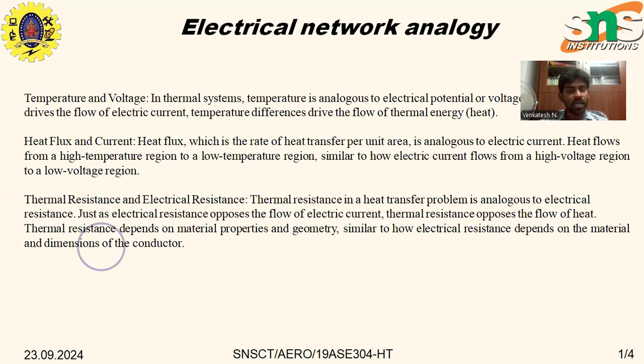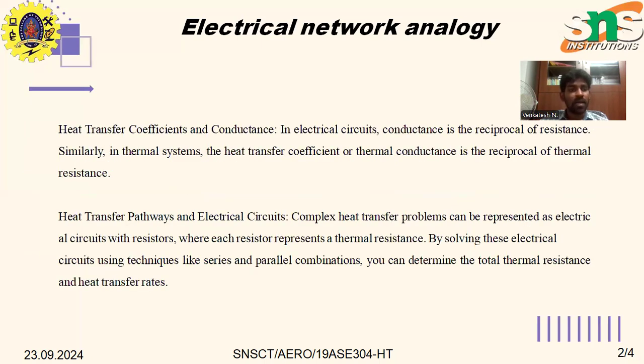Thermal resistance and electrical resistance: the thermal resistance in a heat transfer problem is analogous to electrical resistance. Just as electrical resistance opposes the flow of electric current, thermal resistance opposes the flow of heat. The thermal resistance depends on material properties and geometry, similar to how electrical resistance depends on the material and dimensions of the conductor. Heat transfer coefficients and conductance: in electrical circuits, conductance is the reciprocal of resistance. Similarly, in the thermal system, the heat transfer coefficient or thermal conductance is the reciprocal of thermal resistance.